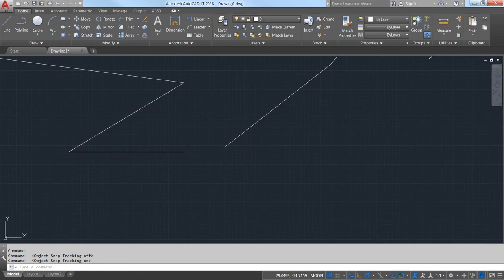If that thing's on, it's almost always going to take precedence over everything else because there's no specific point with the nearest OSNAP. So that one can get you into trouble. I would say don't use that one because it will seem like it has a preference over the others, but in reality, they're all about the same weight.